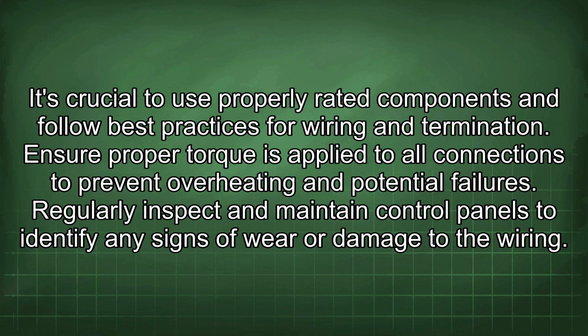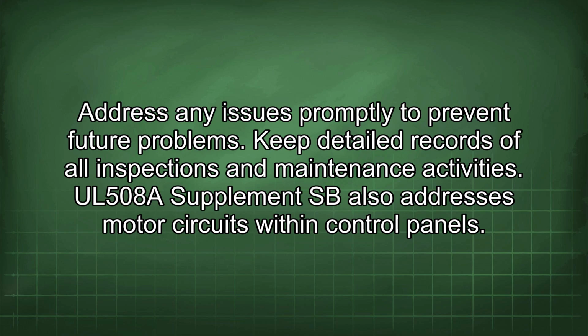Ensure proper torque is applied to all connections to prevent overheating and potential failures. Regularly inspect and maintain control panels to identify any signs of wear or damage to the wiring. Address any issues promptly to prevent future problems. Keep detailed records of all inspections and maintenance activities.